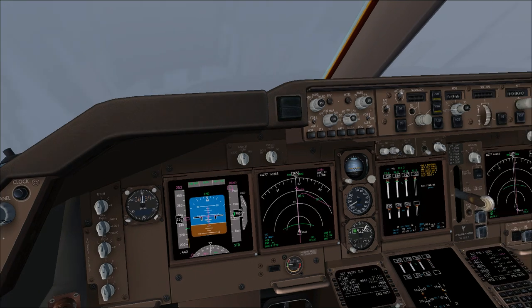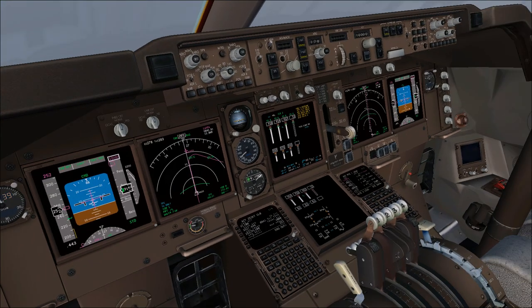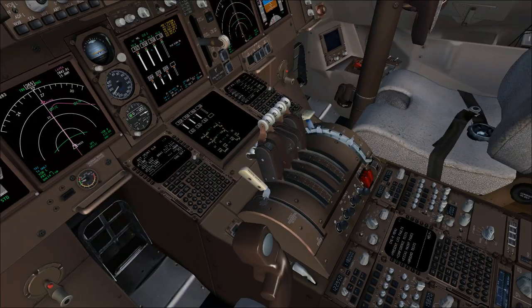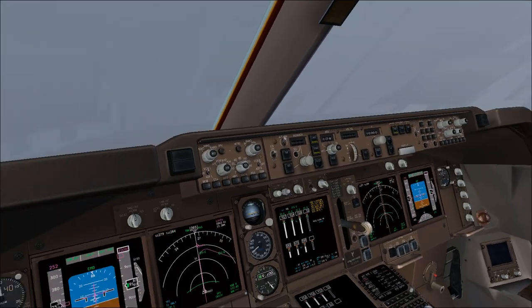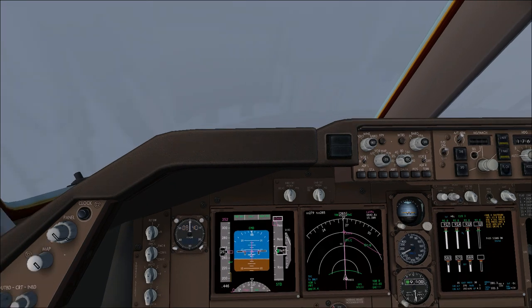After takeoff checklist is landing gear up, flaps are up, auto brake off, landing lights off, and altimeter to standard. This completes the after takeoff checklist, and we are now approaching our cruise altitude of 10,000 feet. The aircraft will actually modify its path. You will see we'll keep speed, LNAV and VNAV path, decreasing the vertical speed and leveling off at 10,000 feet.